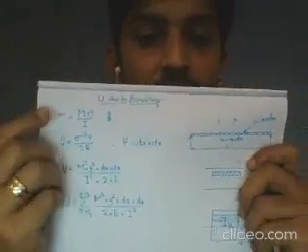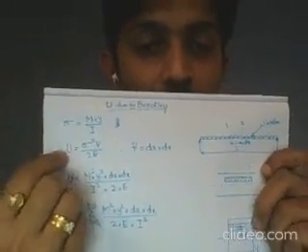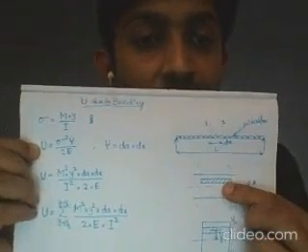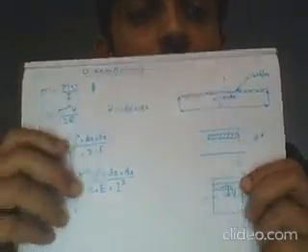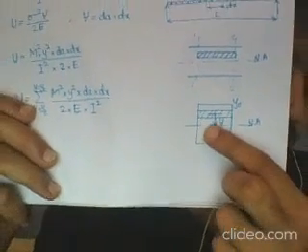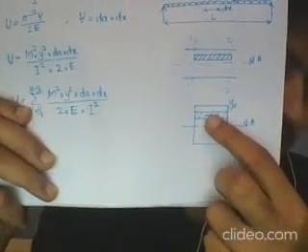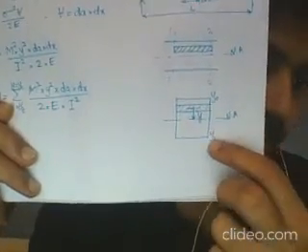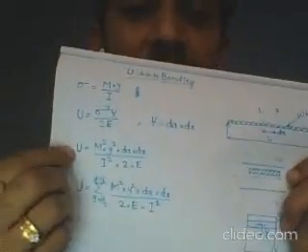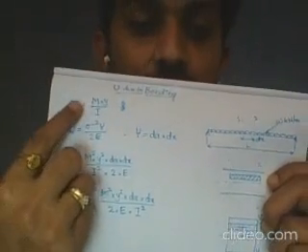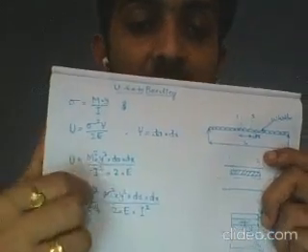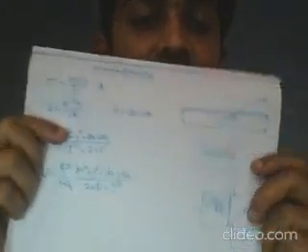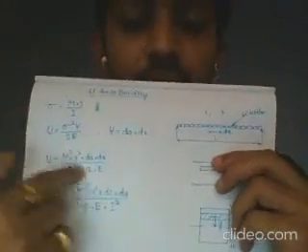So let us recap. I have used a bending equation, then I have used the strain energy equation. I have considered a small element of cross-sectional area dA and length dx. If I find the centroidal distance of that element from the neutral axis and mention the limit it can go to, then using all these parameters I can write strain energy using stress due to bending and the volume of that element. Integrating over multiple elements, for the given limit as well as for the length, I can deduce strain energy due to bending.